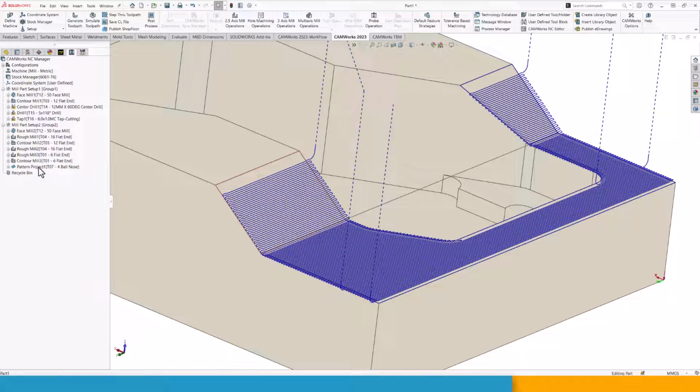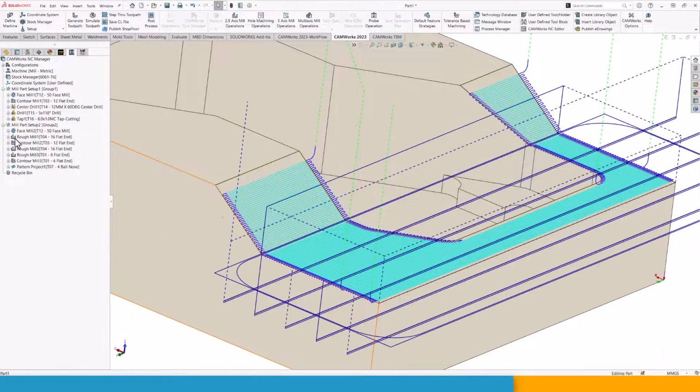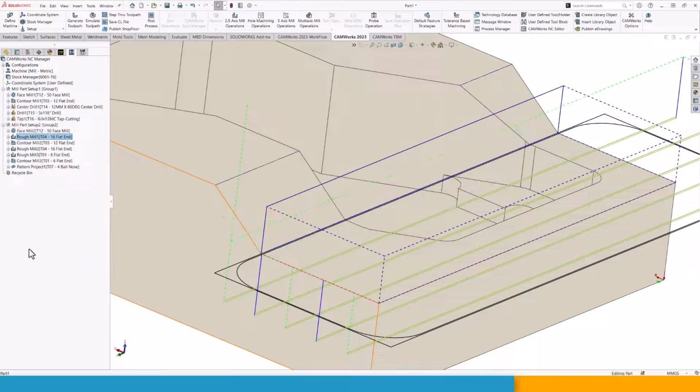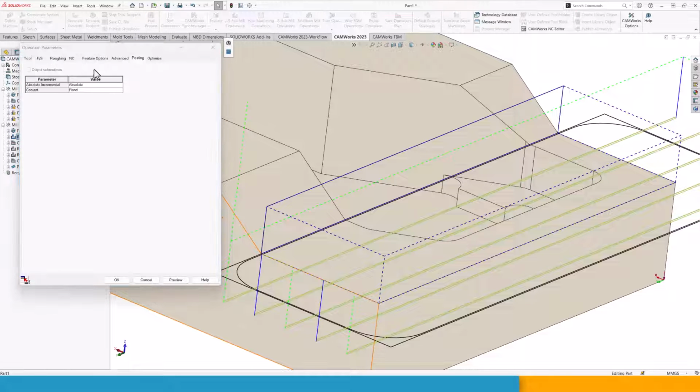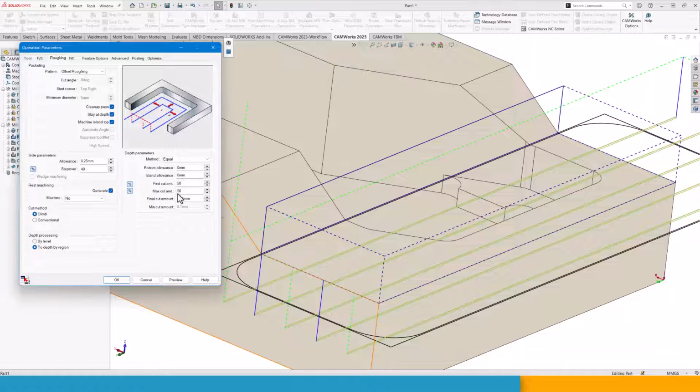Very good. Let's take a look. Now we have these toolpaths, and I know that for this one we might want to do a bit of offset to make sure that we actually have anything to machine, right? So for the rough mill, and it is slightly slow when I'm running the screen recorder as well. So let's just give this, I don't know, 0.5mm. That would be probably okay. And let's do the same over here like that.